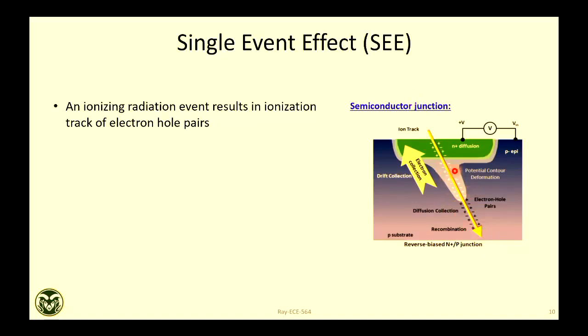And those electrons and holes will be collected by the junction, because in a PN junction you always find an inbuilt electric field. Just like in a solar cell, which is a PN junction. When light falls on this PN junction, it creates electron and hole pairs. You collect electrons from one contact and holes from the other contact. Exactly the same thing is happening, in a much smaller time scale and with a much larger number.